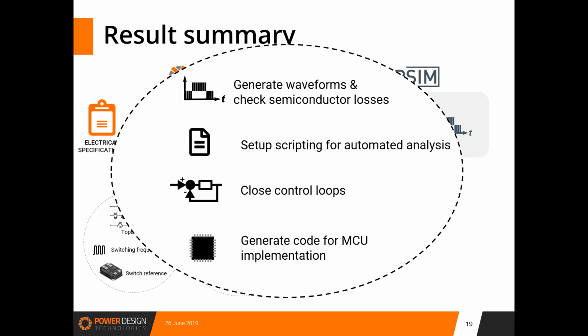Yeah, essentially, PSIM is a general purpose simulator specifically made for power electronics. So you can generate waveforms, check losses, check operating conditions, make sure that your transient temperatures on the devices don't overshoot. You can close the loops, you can generate code, you can add nonlinearities into the system, you can control an actual motor, you can do all sorts of things.